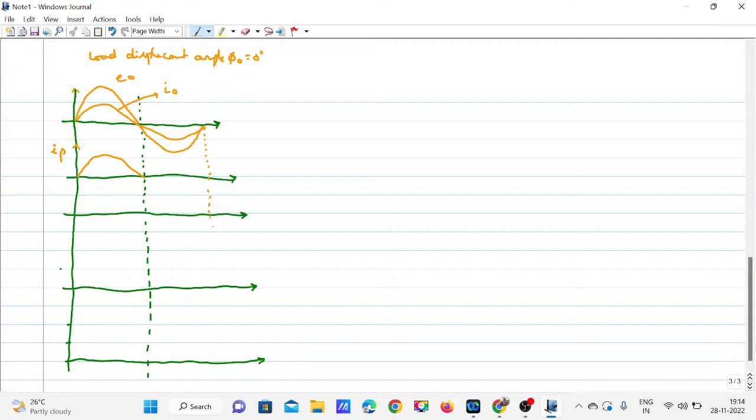So there is no negative thing in it, because if the source is reverse biased, I mean negative, then the diode or thyristor involved there, actually it is a diode only, so we are starting from alpha equal to 0, so we can call it a diode only.